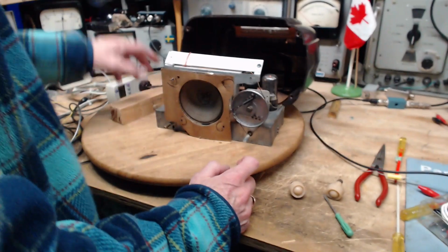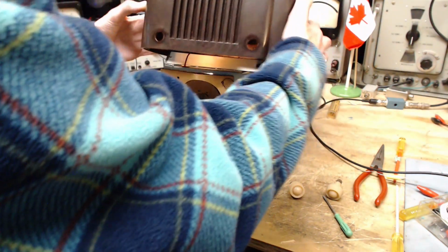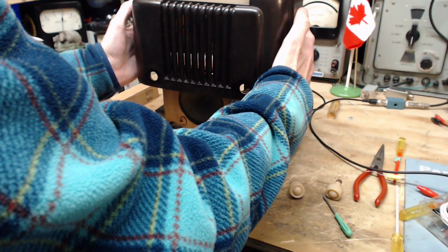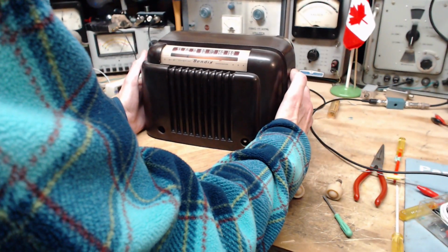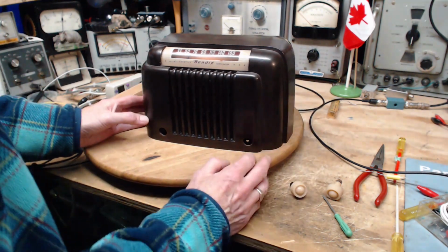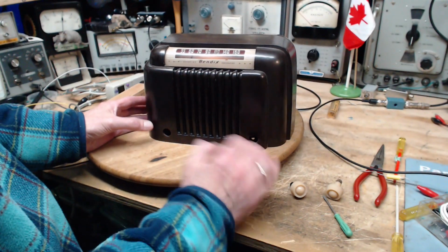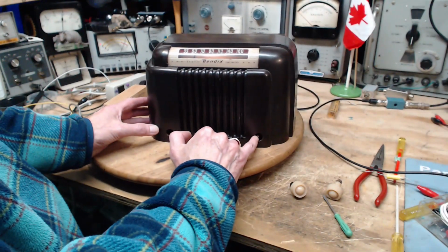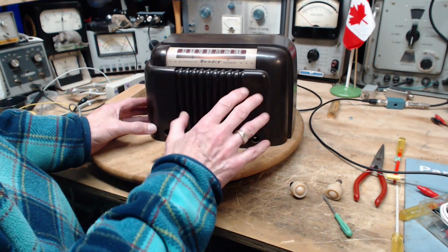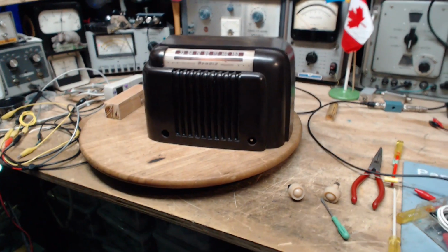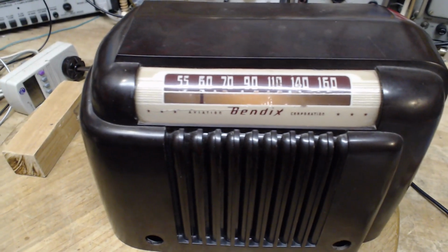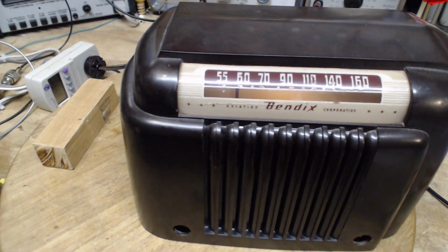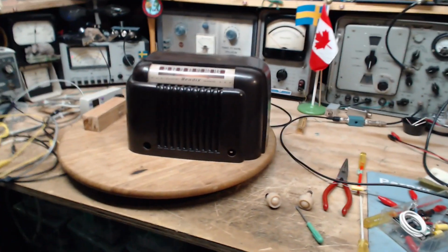Okay, let's put this on. Oh, I got a lot stronger there right at the end, just from the cabinet and the speaker. So I'm looking to make sure these are in the center. This is in the center, the cabinet's in the right position. Let's take a look at where we're tuned. So it should be 590, right on the money, 590. Excellent. That's it. That's the alignment.